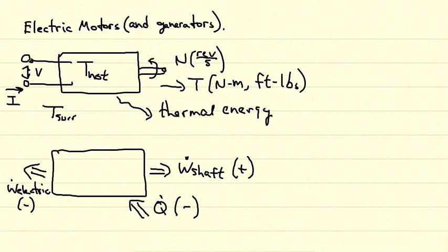Now, my control system itself will have some kind of different properties. There will be a motor temperature, and the energy of the motor and the entropy of the motor. And what I do is I make the assumption that this is all steady state. And so if I make the assumption that I've brought the motor up to temperature, and T motor is no longer changing with time, the energy of the motor is no longer changing with time, its entropy is no longer changing with time, then I can assume that my control system is steady state.